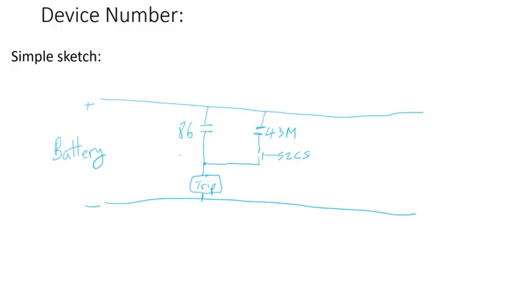So basically you have the batteries providing power, but in this case, since this is normally open, there is no path to the trip coil, so the breaker will not be tripped. And you have a manual. This is 43. It's a switch. M stands for manual, so it's in the manual position. It's going to be in manual or automatic position. So there's no path, so the breaker will not trip.